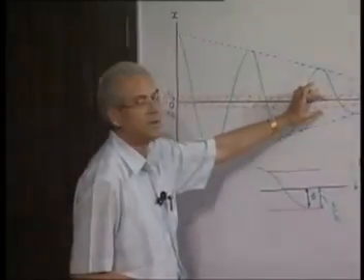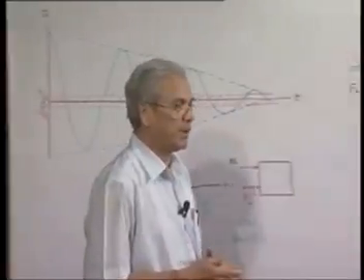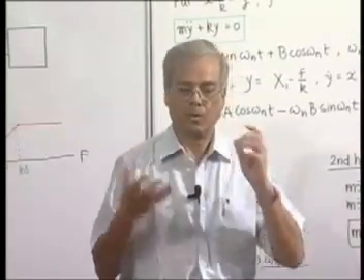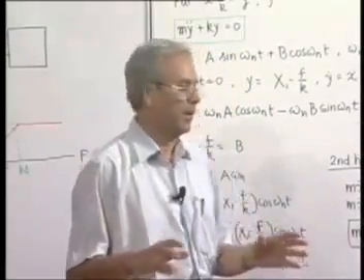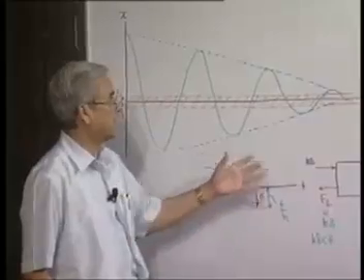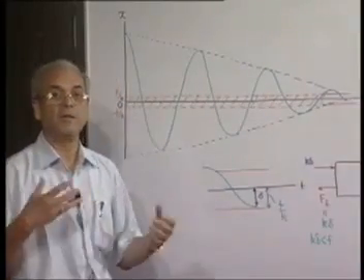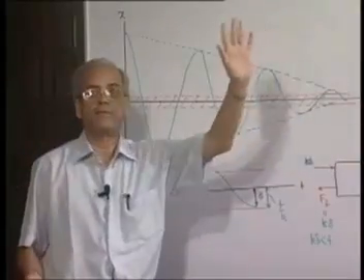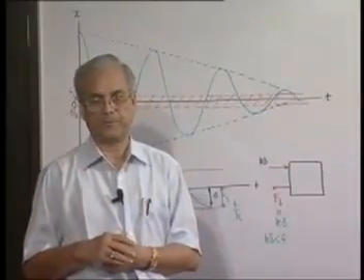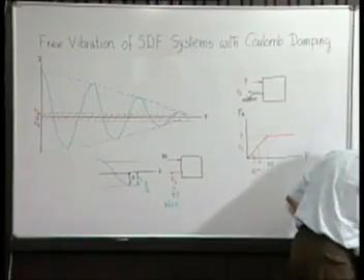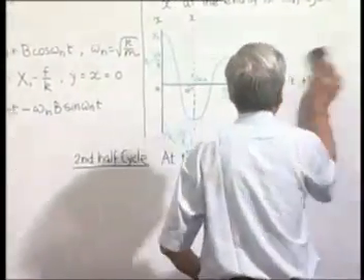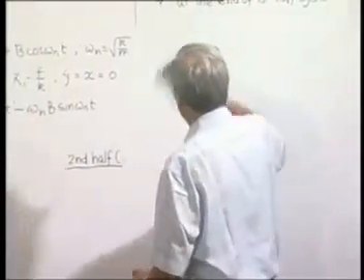happens within this line. And that is what I mentioned once, if you remember, that real systems always come to a total stop, velocity becomes 0, primarily because in all real life systems there is a certain amount of Coulomb damping present. If it is viscous damping, theoretically it should go on ad infinitum, oscillating with smaller and smaller amplitude. Now, this decrease in amplitude per cycle could be found out by another method, which is of course much simpler, as we will see now.